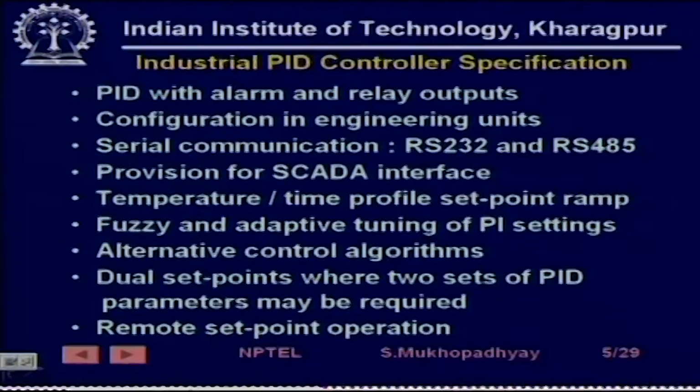So, such facilities have been provided here. And finally, you could have remote set point operation, where this remote set point is actually a subset of SCADA. So, if you have supervisory control from a remote place, then maybe the operator sitting in the control room can give set points. Okay. So, this is what a typical PID controller looks like.